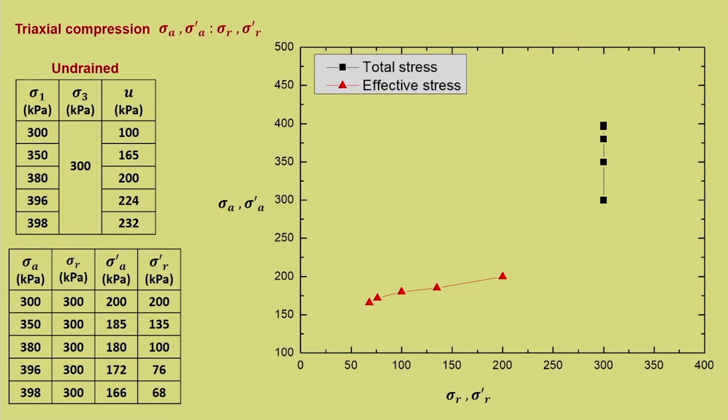Now, things have changed, but you can note that the pattern of the total stress path is more or less the same. But while the total stress path is the same, how the effective stress changes in the undrained test is totally different from what we have seen in the previous slide. Both were vertically rising earlier, but in this particular case you can see that it shifts towards the left. Still, we are not able to make out much from this particular plot.